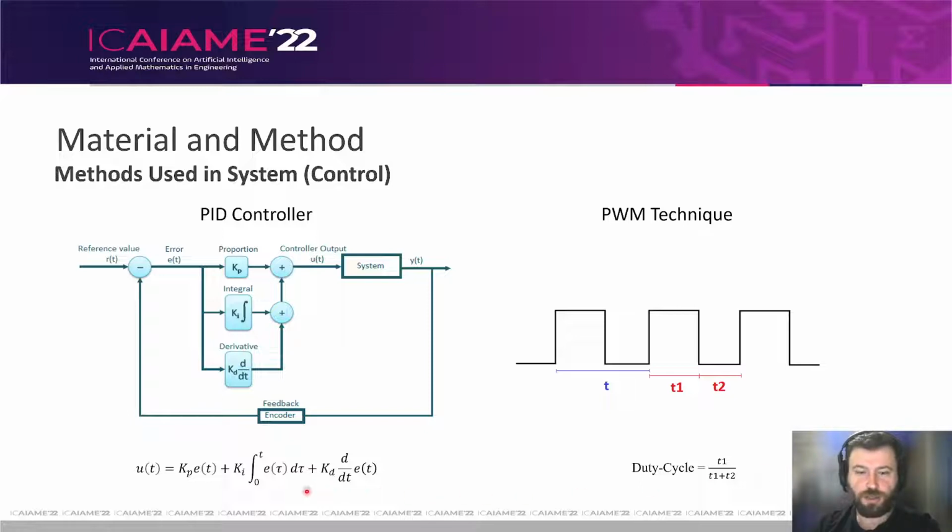In this formula, Kp, Kd and Ki refer to proportional, derivative and integral gain coefficients respectively. Also, E(t) denotes the error signal and U(t) denotes the control output. The feedback signal is required for PID, taken from the encoder on the motor.